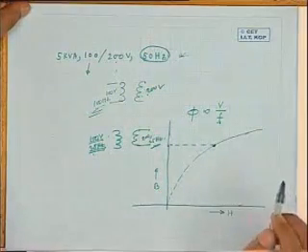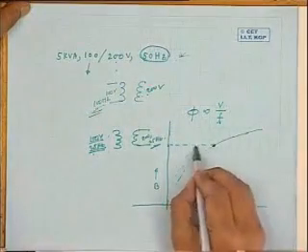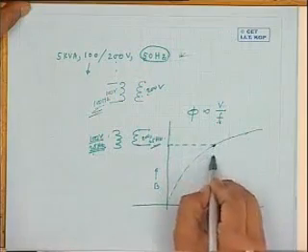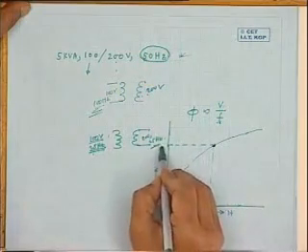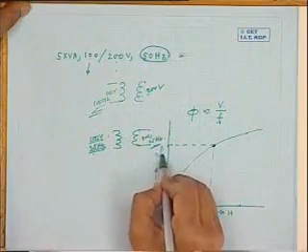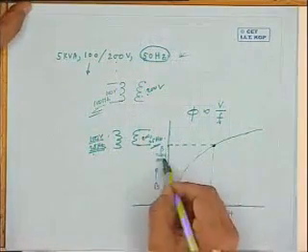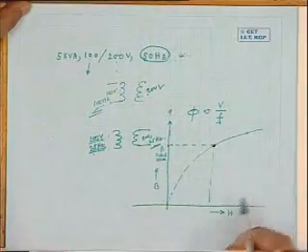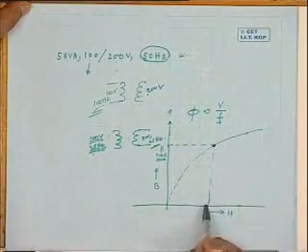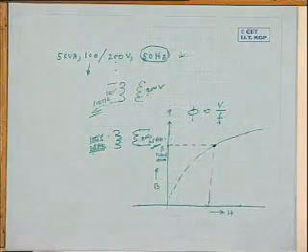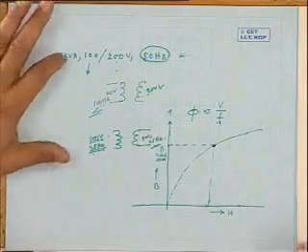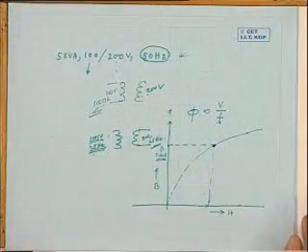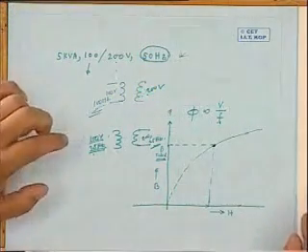And when the transformer is designed, it is designed at what is called the knee point in order to reduce the size of the transformer, etc. You should have, just after the linear portion, at the knee point, the transformer designed. That is, this is the B rated of the transformer. Because core area etc. are constant, this axis can also be treated as flux level. You understand? So suppose this is the rated condition, and this much will be the magnetizing current of the transformer. Okay, 50 hertz operation. This is the rated flux condition.